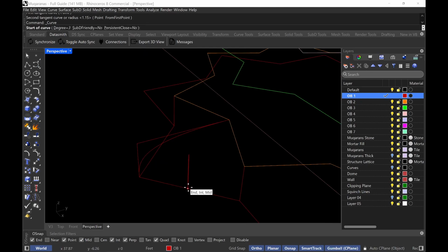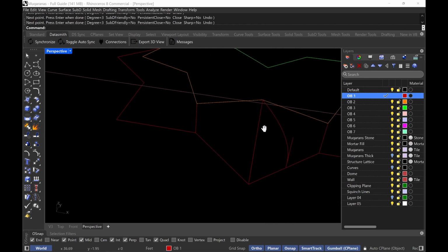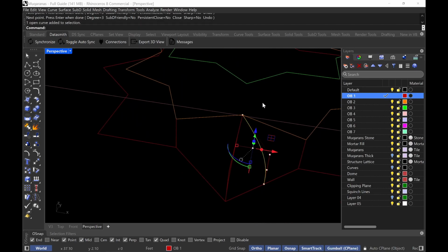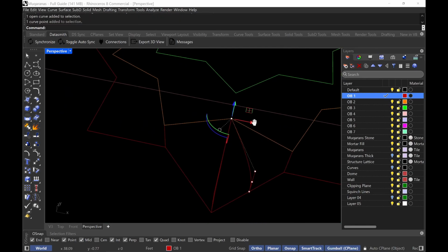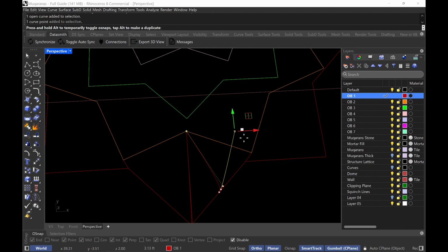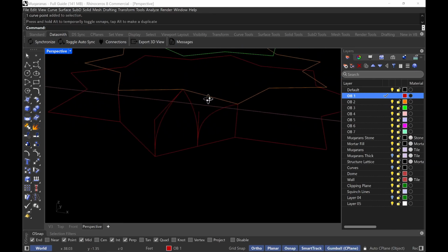So I'm going to go here and do the same thing. Snap here, mid, here, and snap there like that. You see? And I can honestly take this and select this point here like that, and I can hold Alt on my gumball and just drag that there like this. So I have this. You see?